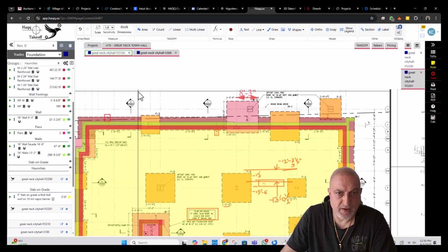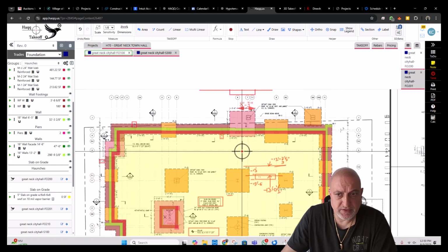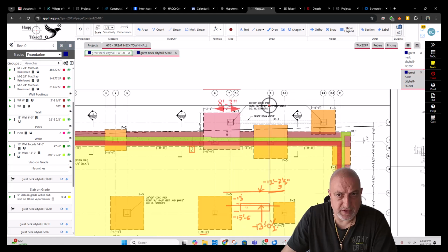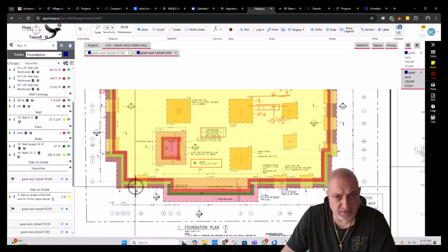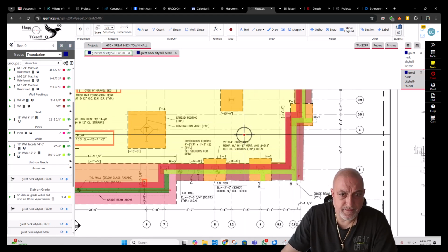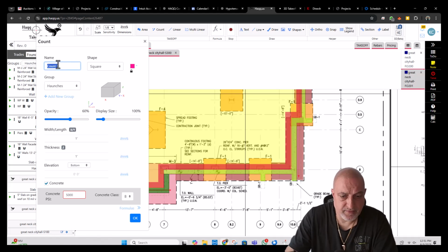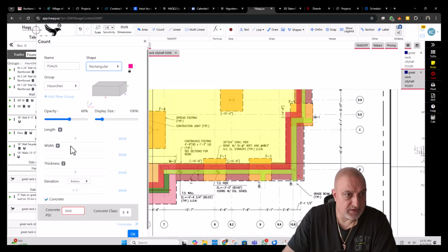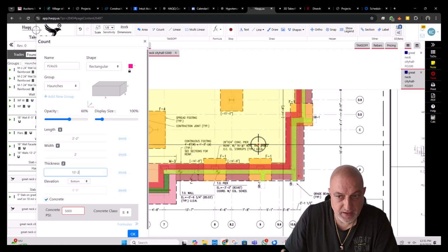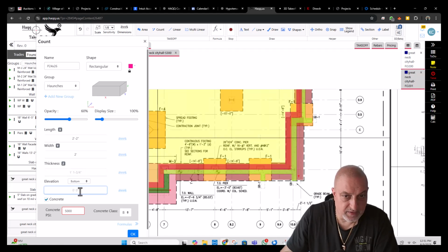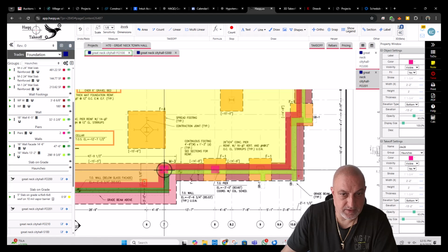Now, what we missed, I don't see the piers. So we can do the piers. Here, 28 by 28 piers, minus 15 feet, and this was 2 inches. And these piers are 13.2. There you go, this is typical. Let's add the piers. P 24 by 26, rectangle, and the sideways is 26. This is 24, 5,000 psi. And the height we said 13.2 was our wall height. The bottom will be minus 13 feet 2.